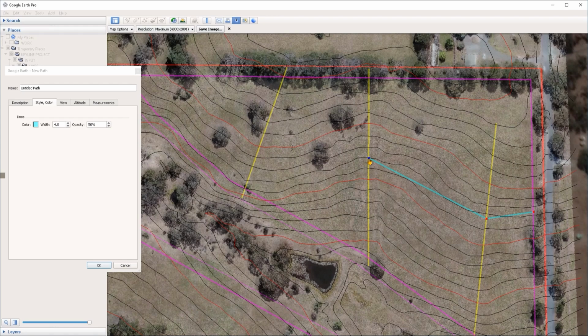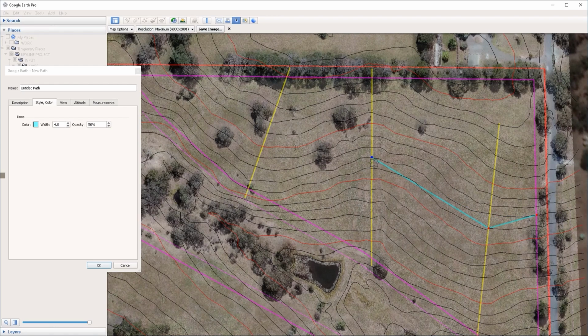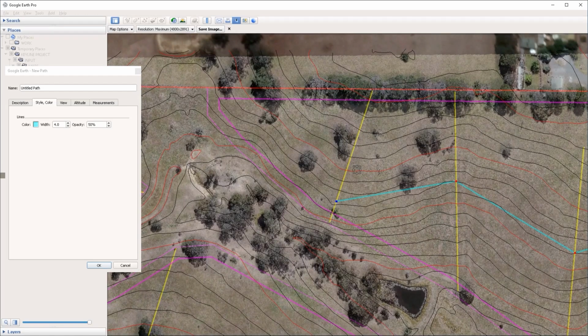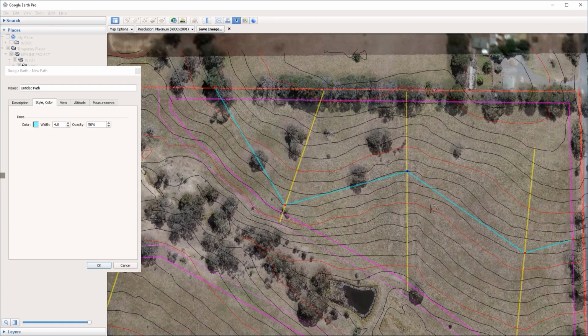Now I'm going to position the guideline here in the middle of the slope, more or less, just so I have more room to work with. I'm going to proceed to this other trajectory line, and we're going to finish off at the boundary. Of course, I'm also trying to keep to the traditional keyline geometry, where we have the line sloping towards the center point of the ridge lines. I'm not going to become overly obsessed about that, however, because the point is to create a functional pattern most of all. If you have to make compromises at some places for the overall good of the pattern design, then this is a good judgment call.